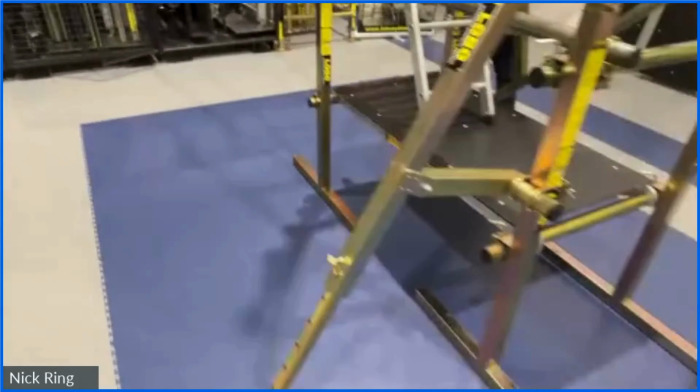We also have a lifting slider beam attachment which fits inside the system. So this is a lifting beam. Now this is 1.2 meters, but this is the 1.8 version. So we do 5 different lengths of these lifting beams because there are 5 different lengths of LOBO board, and they're a matching pair. So now we've put this inside the system. We've locked it down with a LOBO band. You can see from this label, it has a 500 kilogram maximum lifting capacity, and it slides.